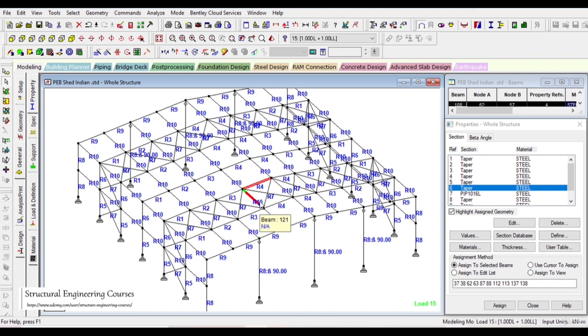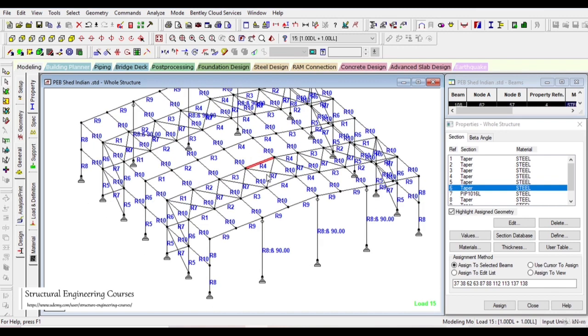and we can discuss more about the technical aspects of how we can economically design the portal PEB trusses, so that we can reduce the role of the bending moment diagrams, and we can increase the role of the axial forces in the structure.